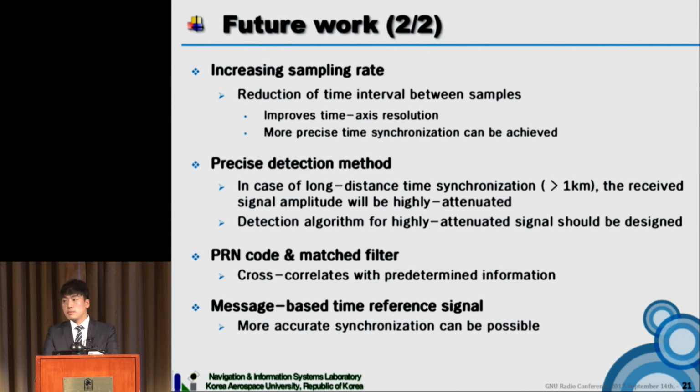In addition, a precise detection method of a valid signal will be considered to prepare a long-distance time synchronization environment. And pseudo-random code, represented as an orthogonal code, and matched filter will be considered, and a message-based time reference signal, similar to a GNSS navigation message, will be continuously considered.